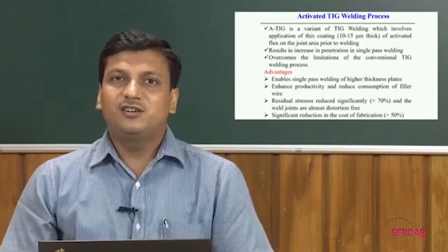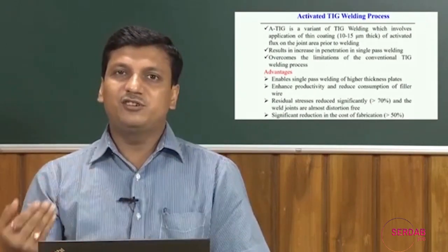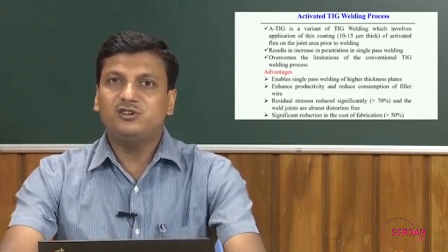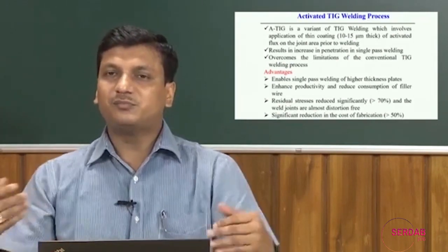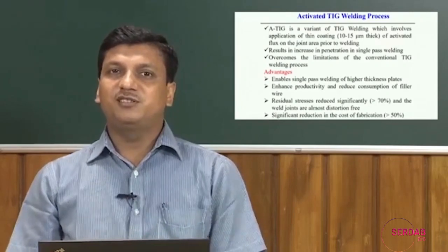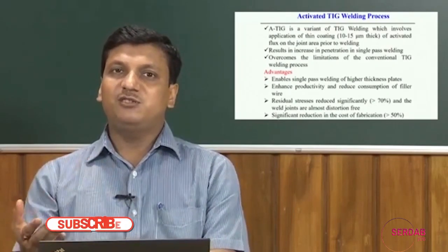But practically, when we try to incorporate the effect of the surface active elements, a prior investigation is required to find out the optimum quantity of the surface active elements for a specific welding system. That is important to know, because at any quantity it may not be possible to achieve the positive effect of the surface active elements.